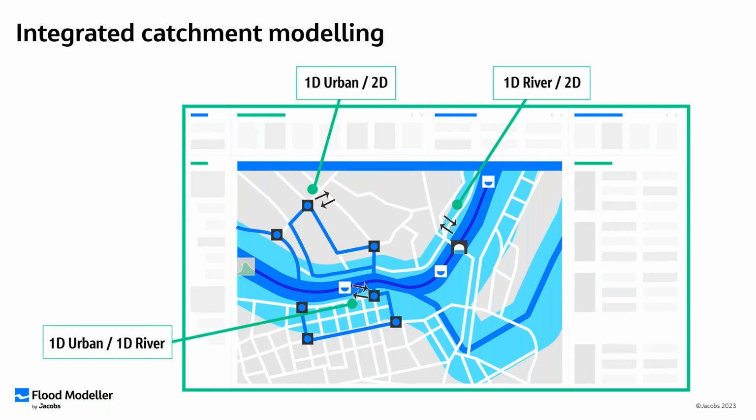And by combining these approaches into an integrated model, we end up with a model that has a wide range of applications, such as the modeling of fluvial flood mechanisms. So we could use a fully linked model to improve understanding of the baseline flood risk in an area, identify the onset of flooding, and key locations where flooding originates from. We might already be aware of fluvial flooding due to overtopping of a riverbank, but integrated modeling may identify further flooding from the drainage network, for example, due to the outfall being inhibited by high water level within the channel.